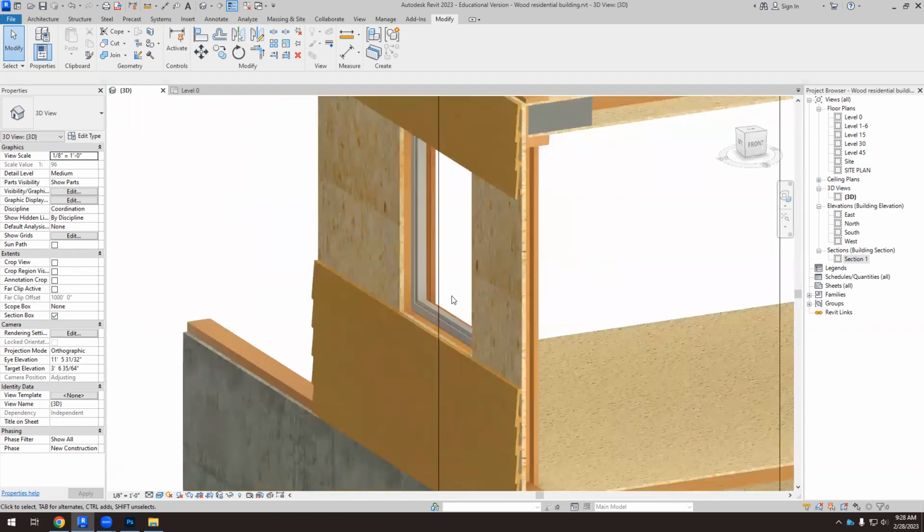So we have created element number one, number 2, number 3, number 4. We have even created these two rubber bands around the window to create the air tightness. And now we're going to do the number 5. But the number 5 is not around the window, it's just in the seal. Okay, if the water comes here, we want to get rid of water. That's why I have created this gap between the fixed frame and this element number 2.